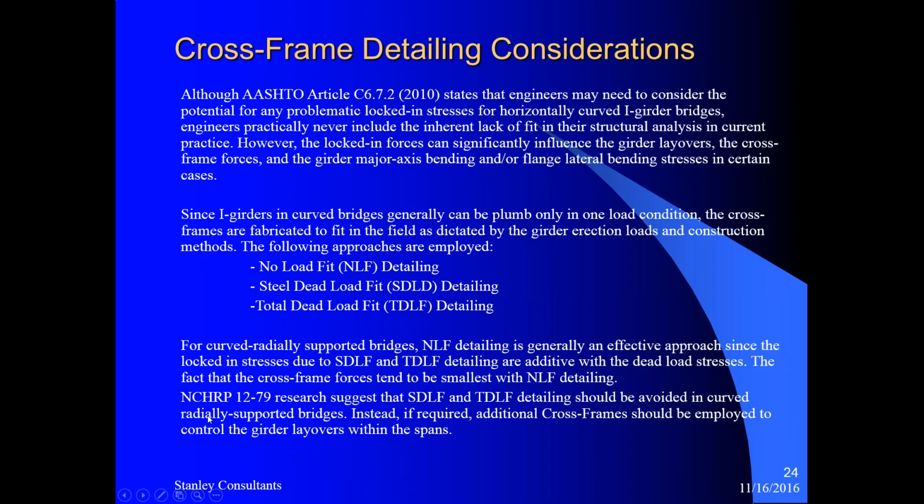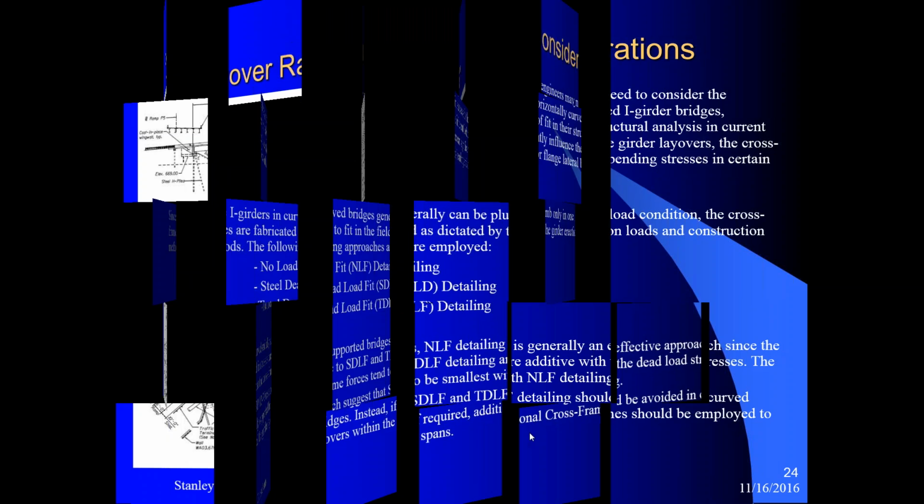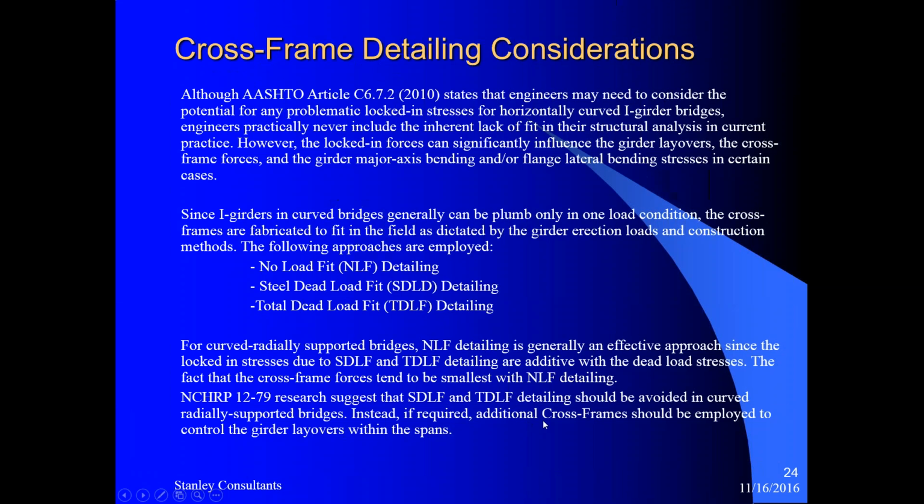However, there is also the NCHRP report 12-79, which recommends that for radially supported girder systems, the no load fit detailing is the best approach.